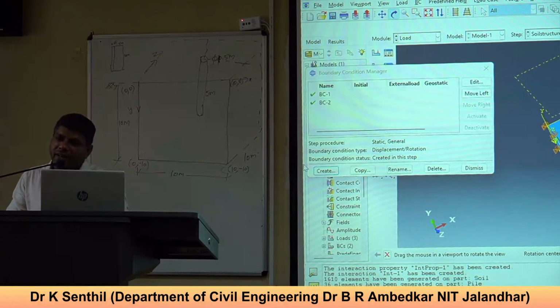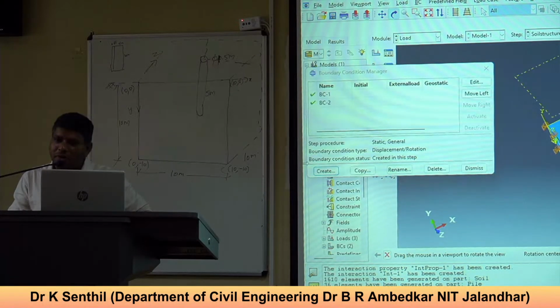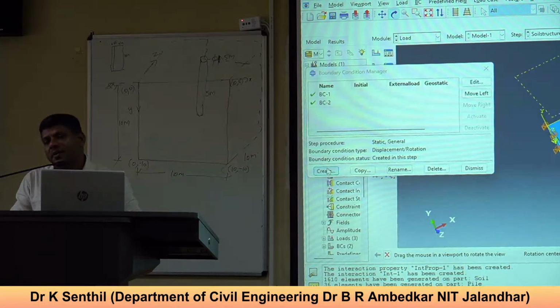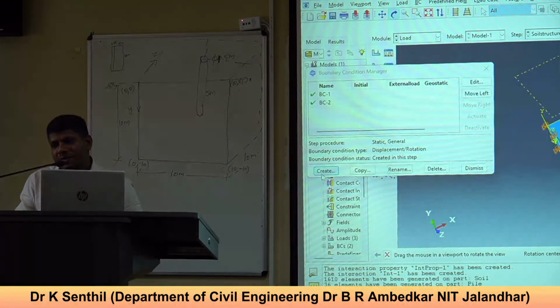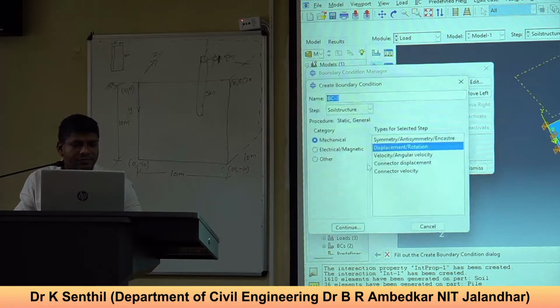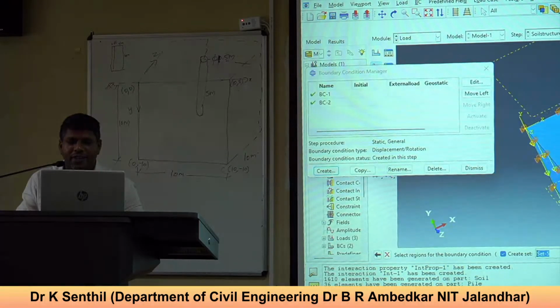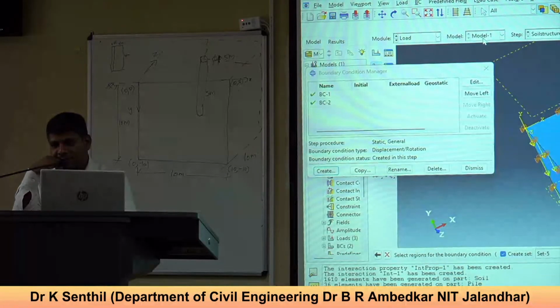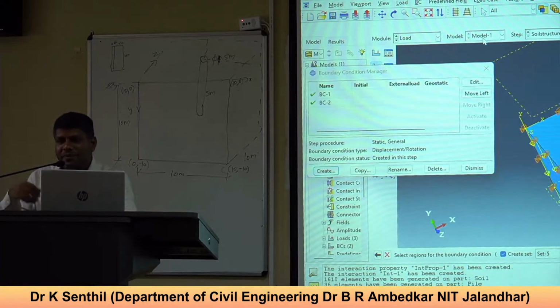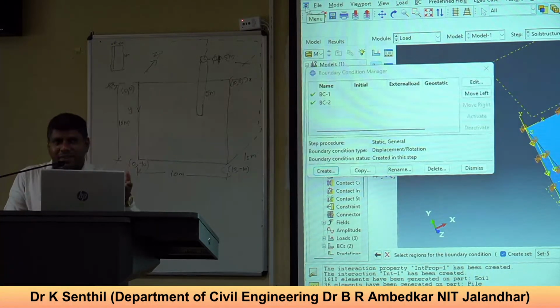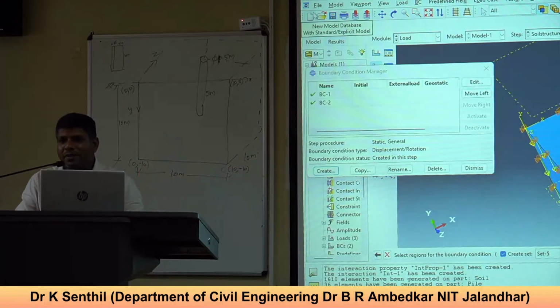No, we have already defined the mass. No, we haven't. We only defined the force. Acha. Okay. And you defined it in the vertical direction. That is the external force coming due to the superstructure. The only way you get these earthquake-related problems, to get the inertial force, you need to create a large mass on it. In FE, you can just have a point mass, but make the point mass very big. Very big, 100 tons.